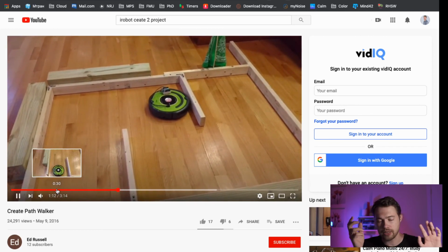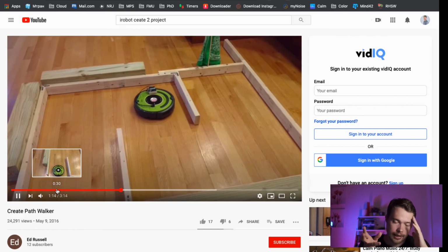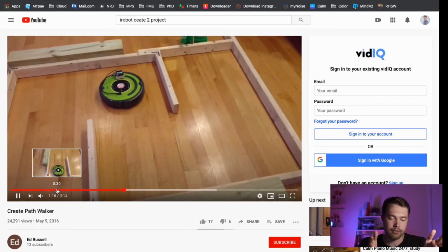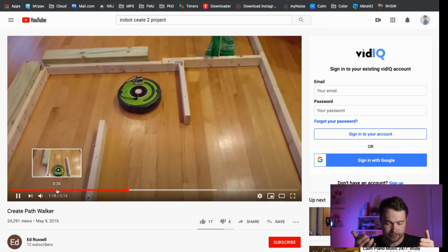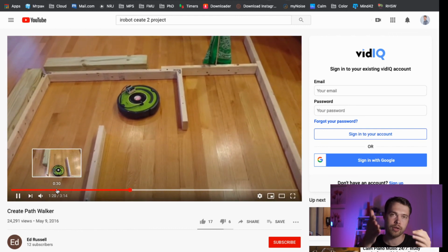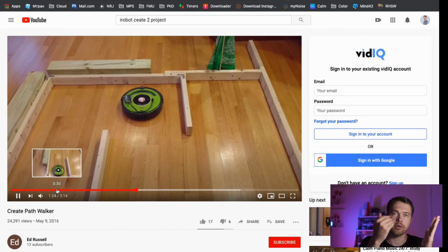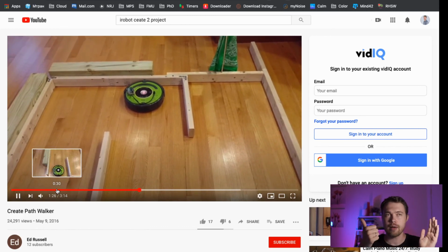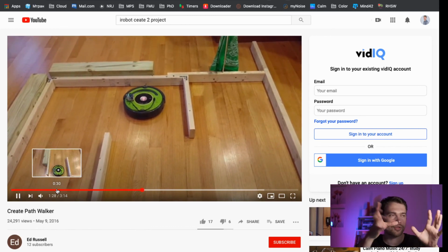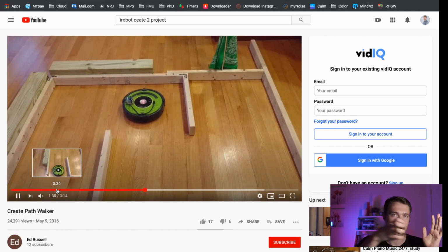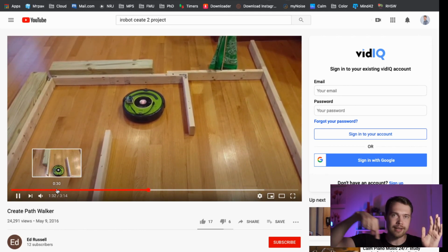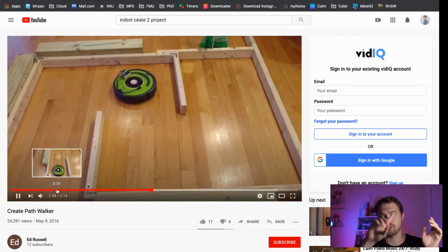Yeah, so now we can see what it does and how it was achieved. You can basically go through that kind of labyrinth, right? How does it do that? It goes forward until it bumps into something, turns left 90 degrees, goes forward, bumps into something. If it happens that it bumped, then it turned left, it bumped again, then you need to turn 180, turn around, and then just go that way.